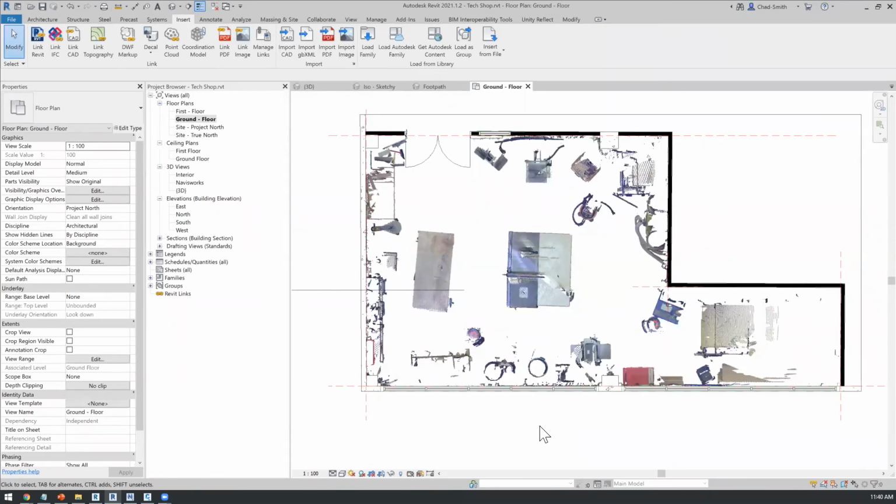I will point out that there are third-party Revit add-on tools from typically surveying or scan vendors that provide add-ins for Revit, AutoCAD, and so forth that can help automate this process. However, if you're not using those third-party add-ins, then it is a case of manually modeling those elements over the top of the scan data.